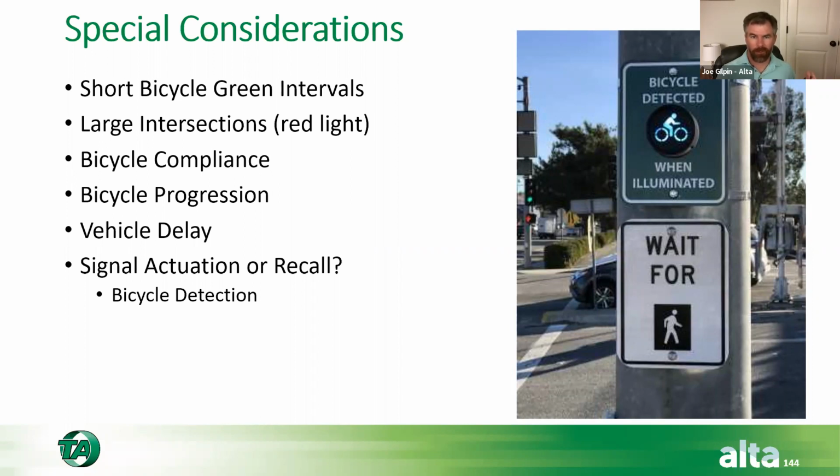And so let's say you've got a larger intersection and you have 45 seconds allocated towards green to a single approach. Now for the bike, if you're using a bicycle signal and you've got a right turn only lane, maybe you're only getting 6 seconds of green out of that 45, so that you can then clear the bikes, turn off the bike signal, and allow those right turns to go through. And so from a bicycle perspective, you're getting a safe crossing, but you're probably going to have to wait to use it. Like 95% of you are probably going to have to wait to use it.